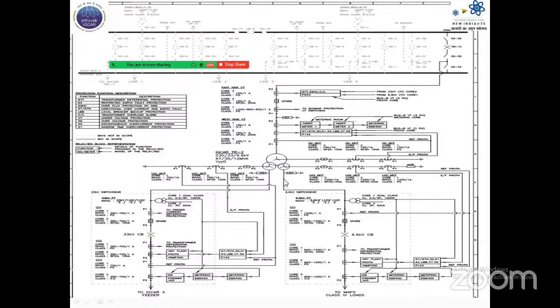This is the single line diagram of the new transformer. Here, a single line diagram is a representation of an electrical system in a single line. So it is a 3-winding transformer, 230 kV primary and 2 secondary windings of LV1 and LV2. The LV1 winding, that is 33 kV winding, is connected to IGCAR through 33 kV switchgear, and this 6.6 kV is connected to MAPS through 6.6 kV switchgear panel. This 230 kV is connected to bus B of 230 kV switchyard inside MAPS.